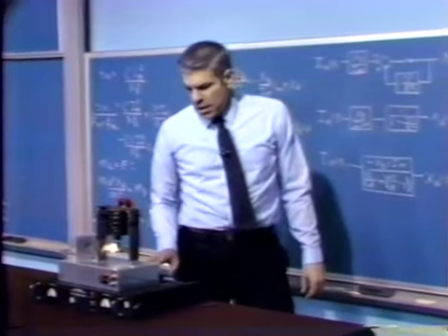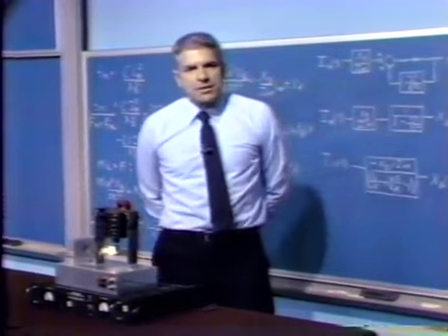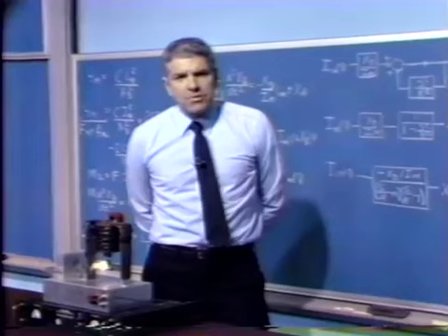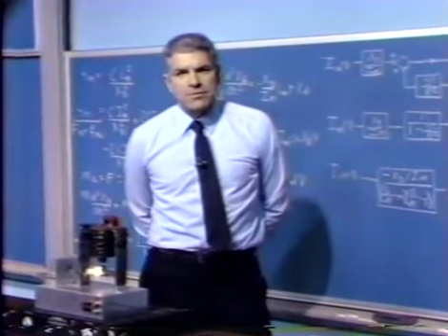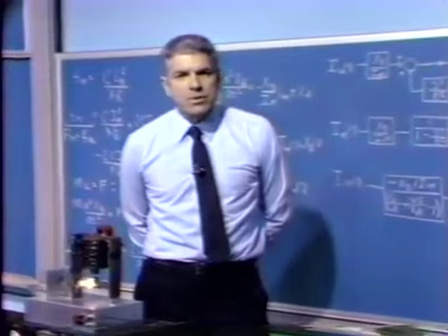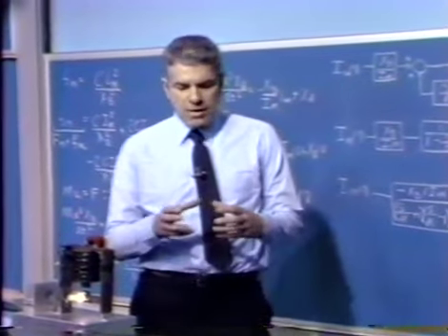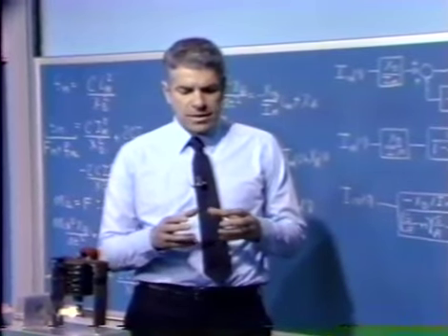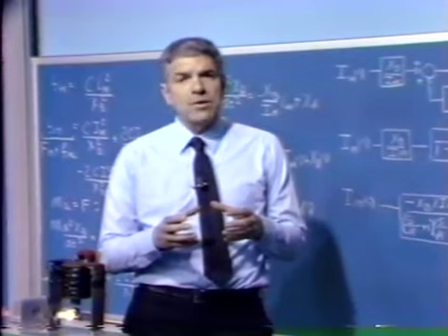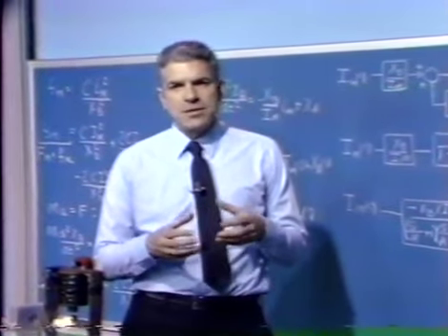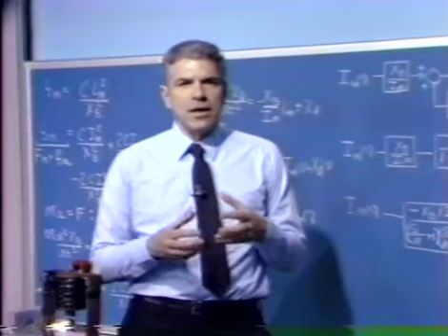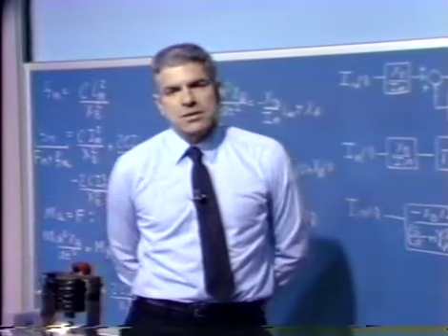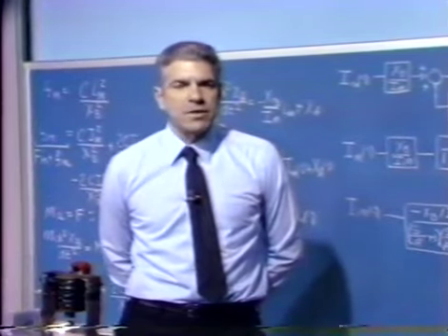There's an interesting variation on this theme that's used in another application. There's an application for a magnetic suspension system for energy storage. If you look at the numbers involved, it happens that you can store energy in a flywheel. If you make the flywheel out of the appropriate materials, composites or something like that, you can store rotational energy in a flywheel, and the energy density is comparable to that of chemical fuels. You can get, for a given mass of flywheel, energy storage that's roughly comparable to the same mass of a fuel.